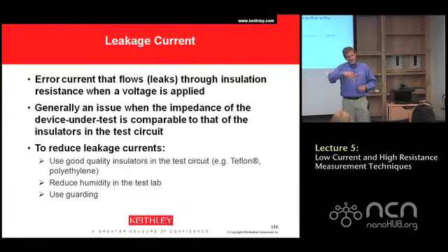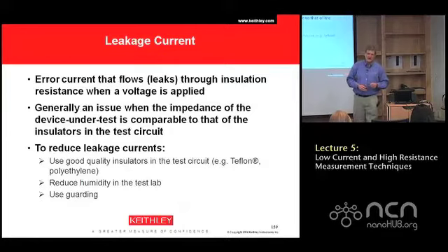Well, it was because that humidity changed overnight. It contaminated enough of that instrument that it hadn't recovered yet. Okay. But Keithley's preamplifiers are hermetically sealed. So we didn't suffer from that particular contamination. So you'll see that a lot, and it shows up a lot, particularly in quasi-static CV measurements.